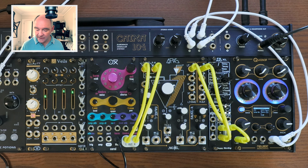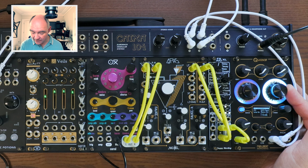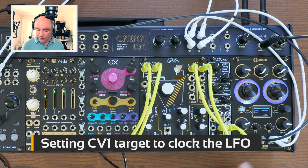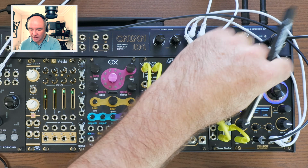Now speed sync syncs the LFO to an external clock source. And I'll show you how to set the clock source in a second. But first we need to set the multiplier. And we can use the big knob now to adjust either the multiplier or divider of the clock. Now we need to set the target of what CV1 controls. So we've set what the LFO is doing on the Quasar, but we still need to connect it to that CV. And right now the target is set to none.